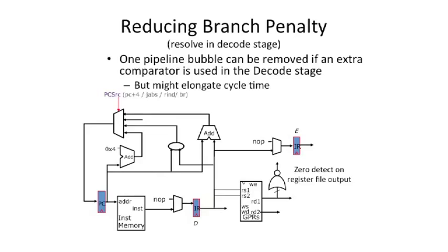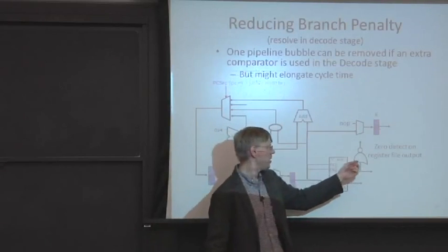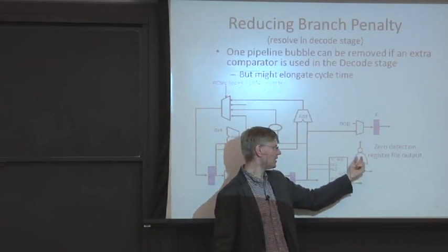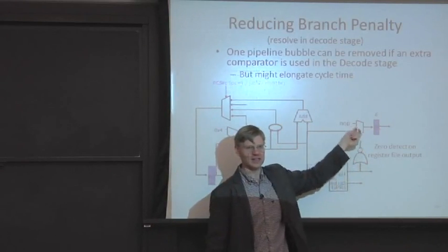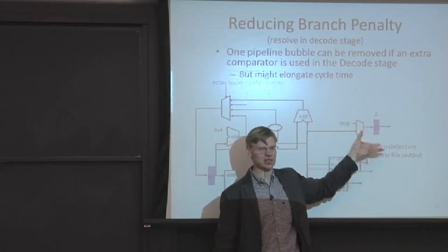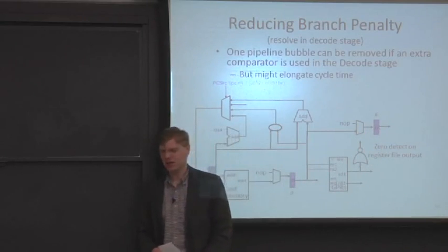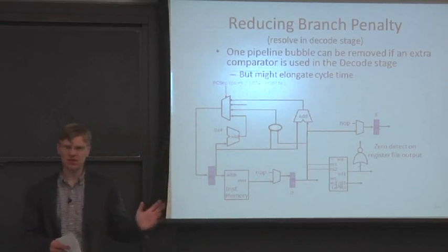Because to do a 0 detect, you can basically build an optimized OR tree and then take the negation of it. Sometimes people even do this with wired-OR or more analog-y circuits. But this is effectively a big OR gate where you OR in all 32 bits if you have a 32-bit processor, and then take the NOT of the output bit. And this is easy for zero detect.